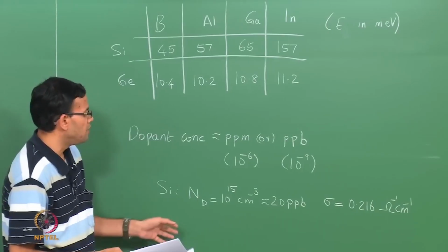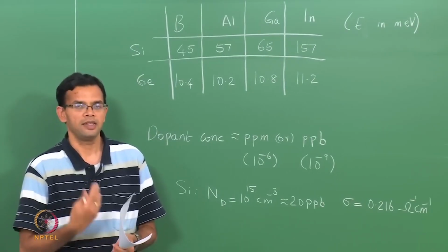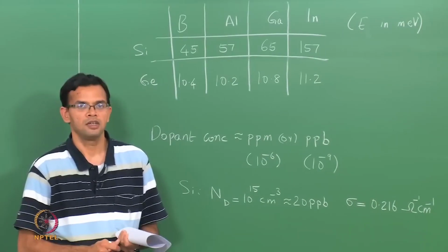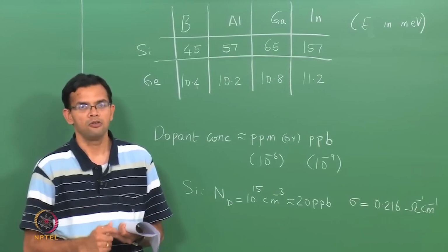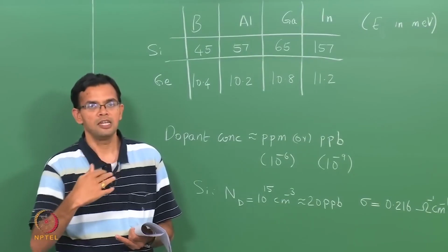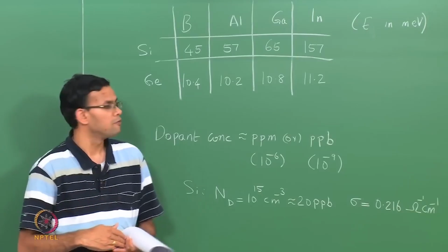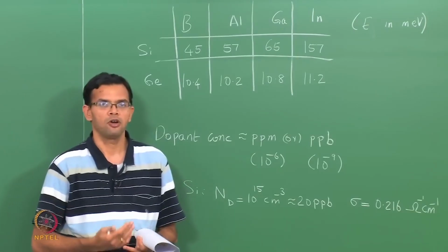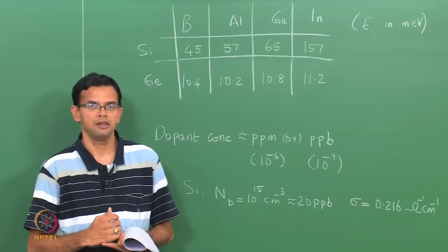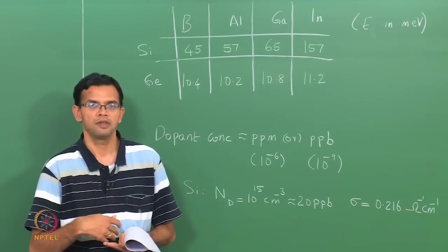We can do something similar in the case of doping in semiconductors as well. If you want to dope n type, you have a source of your n type material. This could be in the gas phase, or these could be ion implanted onto the surface. We will see what ion implantation is later, so that these can then diffuse into the surface and from the surface into the bulk. If you want to do compensation doping, we saw compensation doping last class, where you start with an n type semiconductor and then you make it p type by adding excess dopants of the other type.